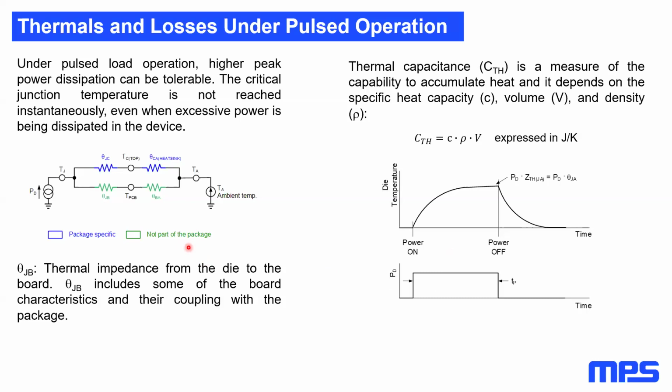Thermal design is intended to reduce each thermal resistance described here, so as to reduce the thermal resistance of the heat dissipation path from the chip to the atmosphere. So in a system, we typically have two paths conducting the heat away from the chip. One goes from the junction through the package into the ambient. Another one travels along the board to end up also in the ambient.